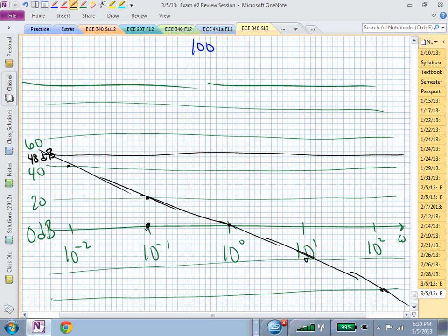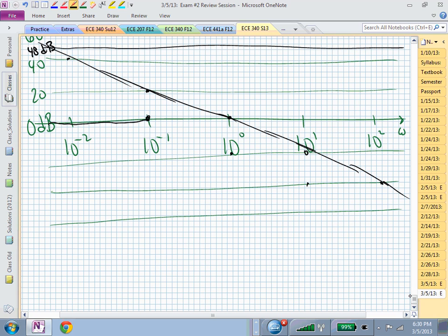So now I'm starting there, I'm 0, and then I start to go down at 20 dB per decade. Then I had a pole at 2, which is 30% of the distance between 1 and 10. And now I go down 20 dB per decade there. So here at 20, I'm down 20 dB.